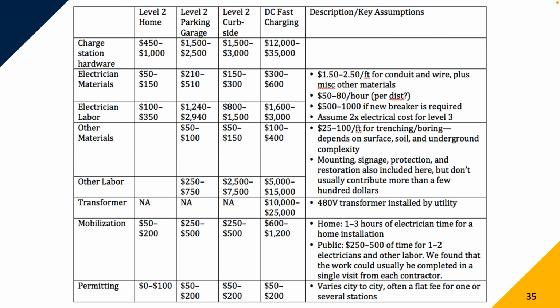One of the things that they do is there is a larger sort of buffer range at the bottom and top state of charge that you're basically not allowed to access. So if, let's say hypothetically, you have a 100 kilowatt hour battery, they might say you can only go from 15% state of charge up to 85% state of charge.